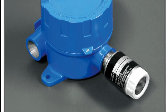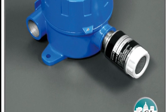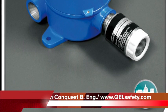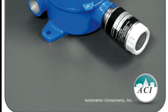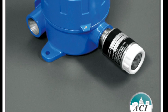Another big application for the infrared sensor is for alcohol storage facilities. For example, if you're bottling Crown Royal or aging it, that's usually in a large warehouse, and there's always a constant, comfortable fumes of alcohol in there. Traditionally, combustible or catalytic sensors would only last about 6 months, and they have to be calibrated every month.